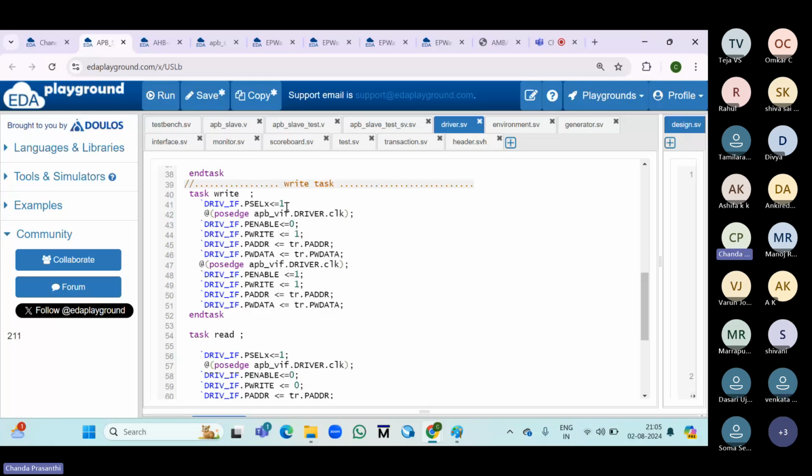That's what I am telling you. If it is Verilog, you can put directly address equal to address, write data equal to write data, enable equal to enable, read data equal to read data. But here, if you put both same, what happened? Where are you doing the randomizing? We are randomizing the data from the transaction class only, right? In the transaction class only, we have the randomized data. That randomized data you are sending to the DUT. Where do we have the DUT? Through the interface, we are connecting to the DUT. So directly how will you send?